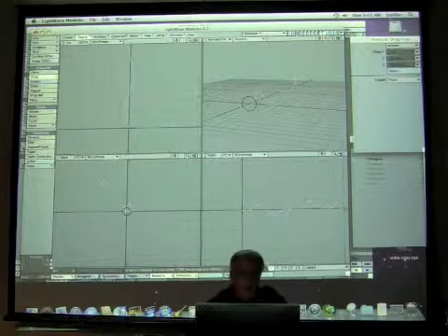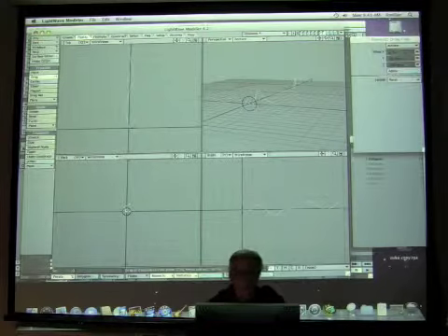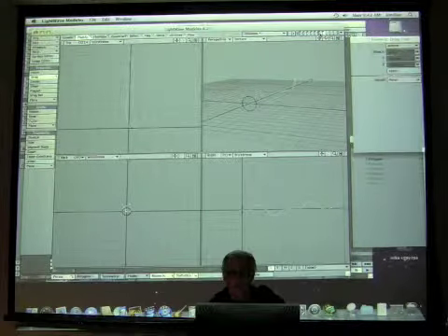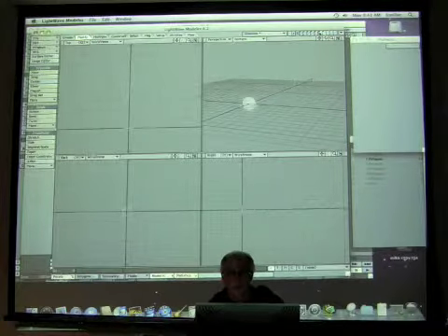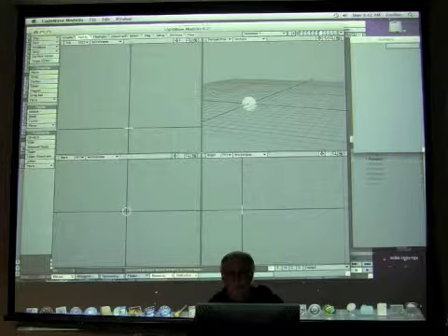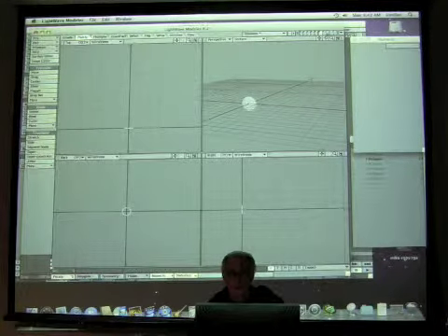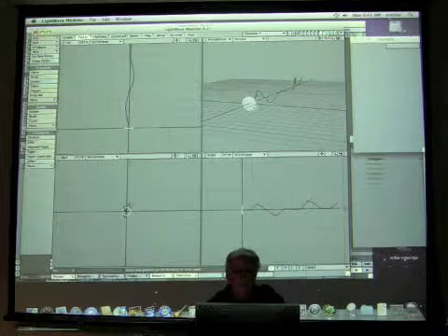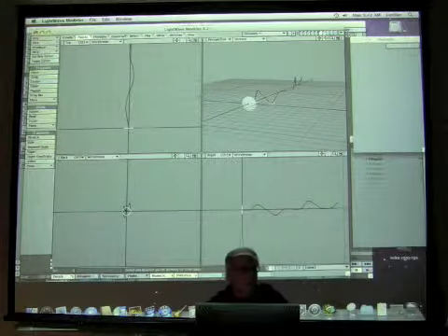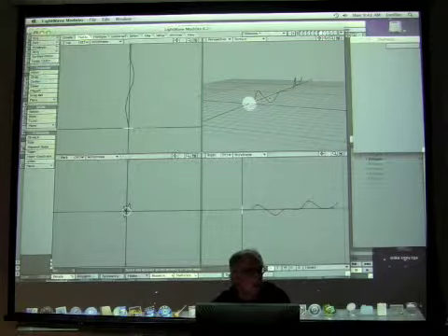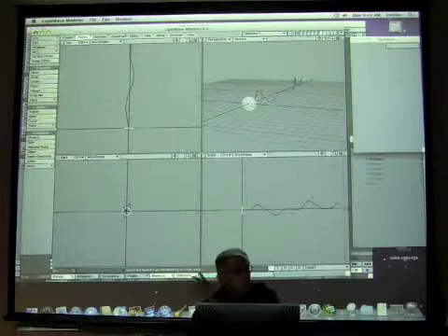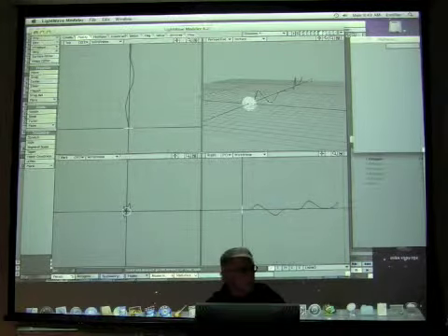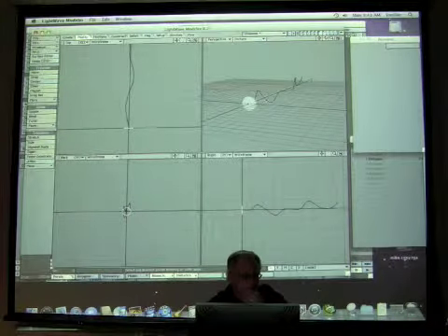So now what I'm going to do is, I guess I need to, I'd flipped it when I shouldn't have. There we go. It looks right. So now I have the disk in the foreground, I have the path in the background. I want the disk to extrude and to follow along that path to create my wire, my hose, my whatever.